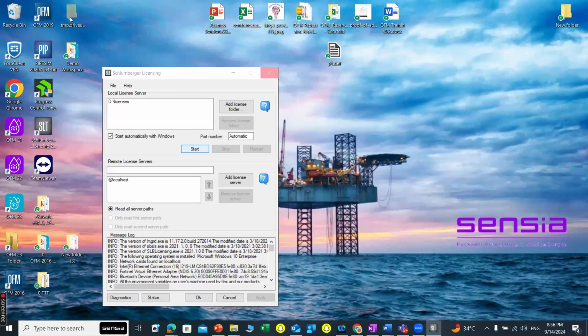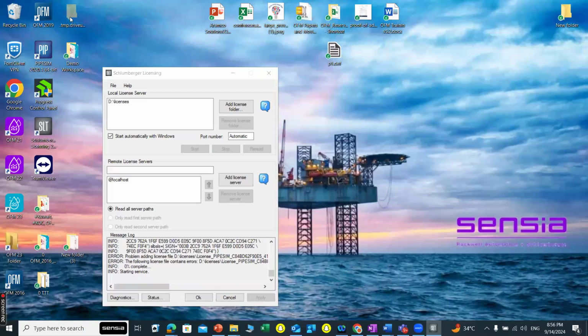I think I have some questions in the chat. What water cut level? Yes. It's based on your facility, how much your separators and other things can handle, right? Based on your plant. Production engineers know that limit. So sometimes you have an 80% limit, or 90%, based on the field, the plant, and the facilities. How much water can you handle, right?